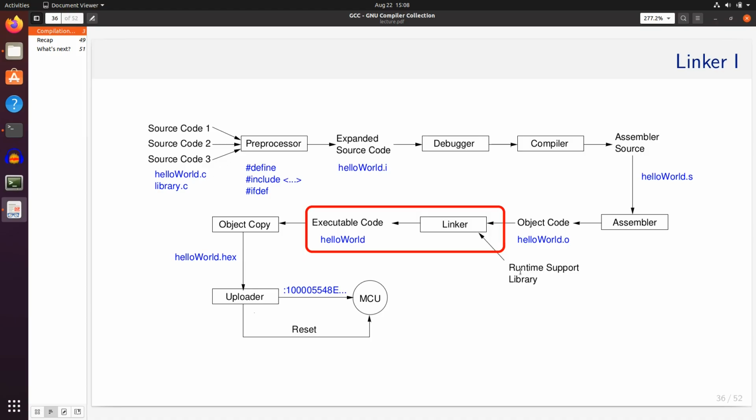What I would like is a library that contains all I2C functionalities, and together with the main, which sends a 1 or 0 over the I2C bus, combining in the linker and get executable code. The advantage is that I can write other programs and just combine the libraries into it to get I2C functionality.